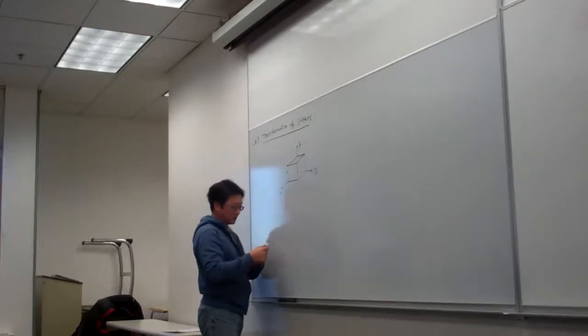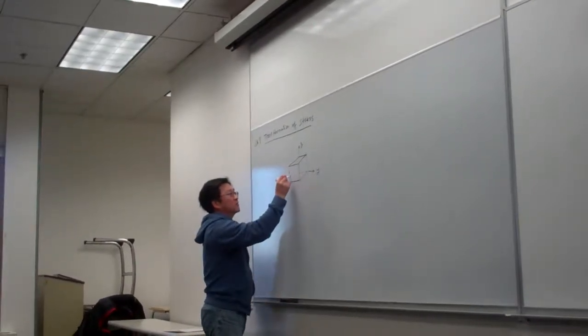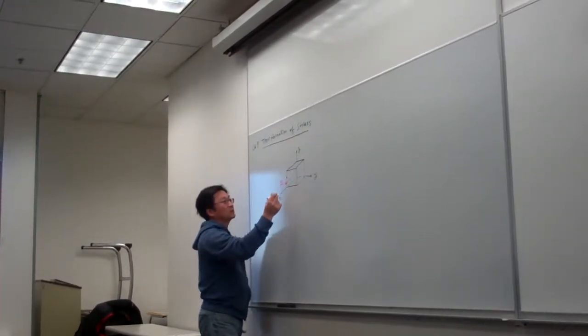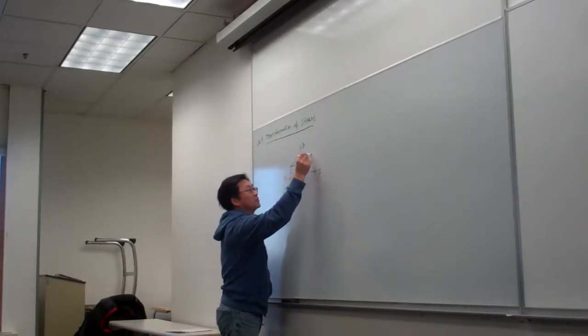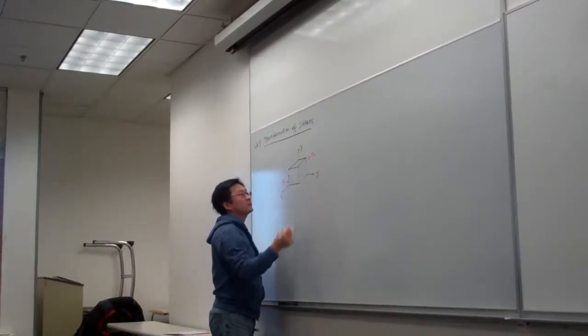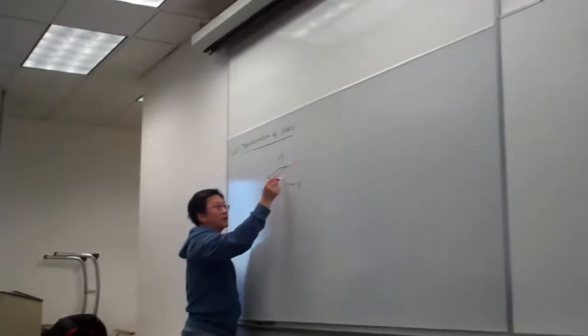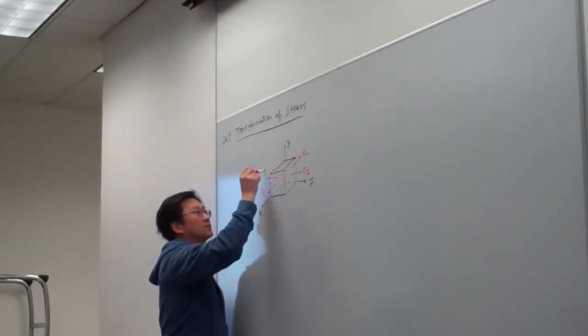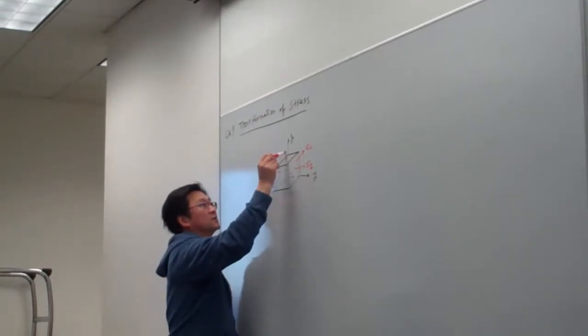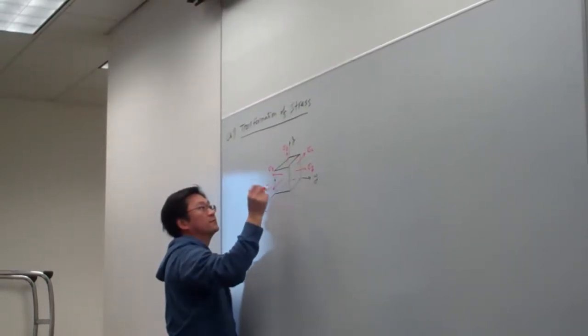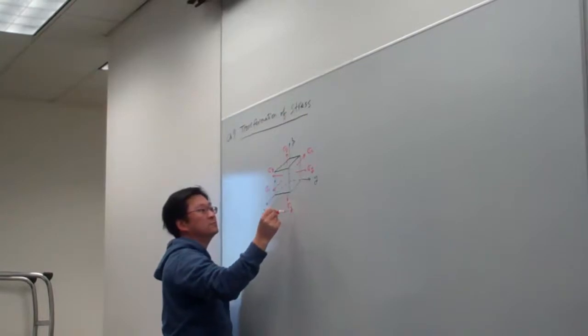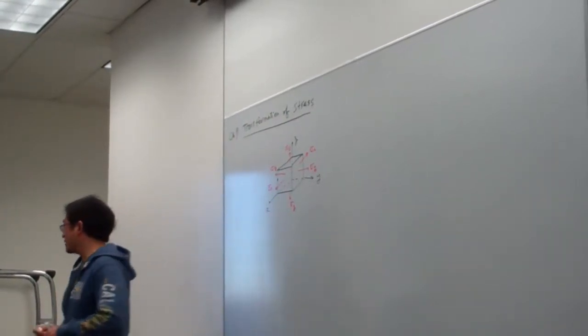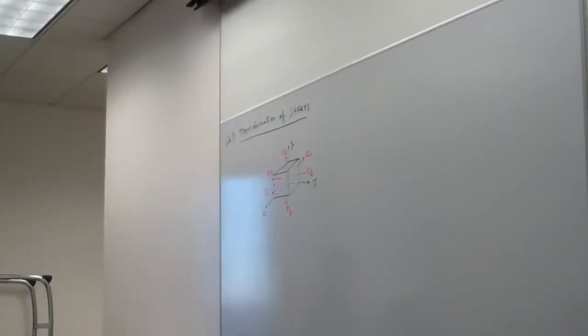For example, here will be the normal stress in sigma x direction, and in balance, the back will have the same value. In general, you might have the stress in sigma y direction on the back in balance, and then in the z direction, normal stress sigma z. Okay, so that is based upon the result of the combined loading.